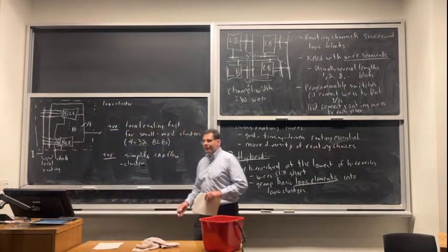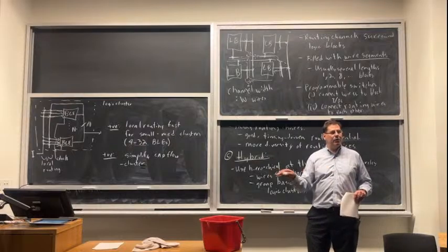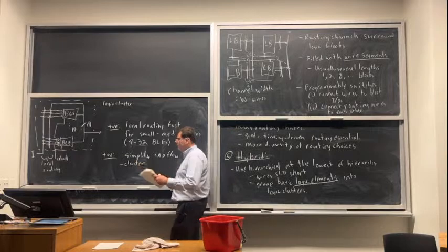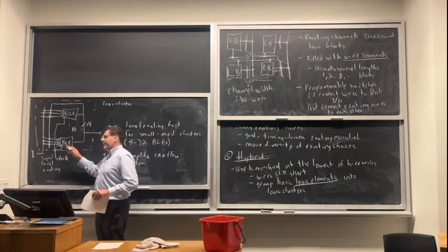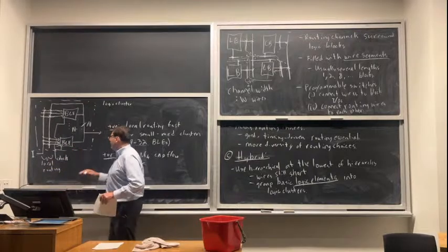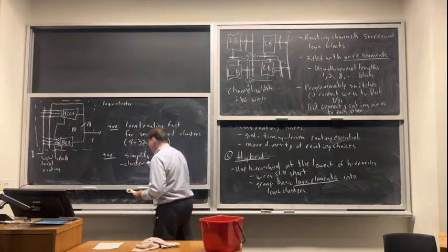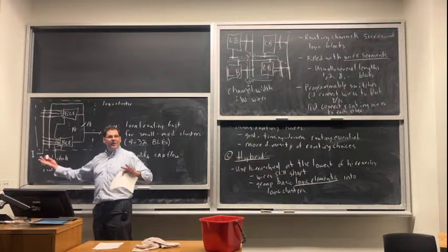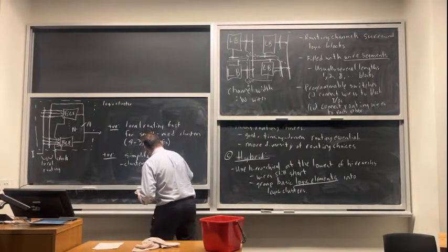For classic hierarchical FPGAs, you started by cutting the circuit in half, and then you cut the halves into quarters and so on. Clustering is the same problem, but instead of cutting it into a few things, you're cutting it into a lot of things. And usually the algorithms that are used are a bit different. So we can use clustering, which is related to partitioning, but it is trying to make a lot of partitions, a lot of clusters.